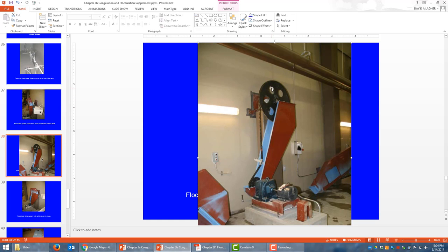And the reason they do that is we need a pretty slow shaft speed, but motors don't like to travel too slow. And in fact, this gearbox is probably taking a motor that's traveling quite fast and slowing it down to turn this one, and then slowing it down even further, just like on your bike, fast in front. Well, on your bike it's big in front and little in back, but we're doing just the opposite. We have a fast motion here and we want a slower motion here.